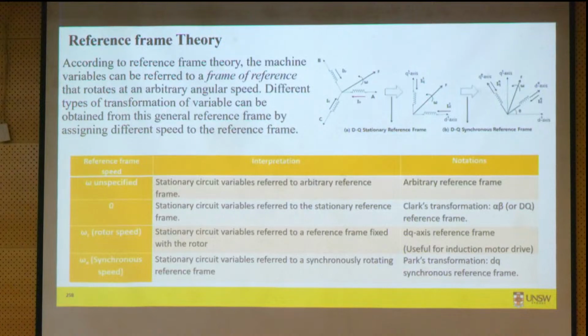We can get the same rotating magnetic field that we get with balanced three-phase current also with two-phase. That means if we have two windings 90 degrees to each other and pass equivalent current instead of Ia, Ib, Ic, we should get the same rotating magnetic field. Based on that, the reference frame theory or transformation has come about. So this two-phase could be a fictitious two-phase.